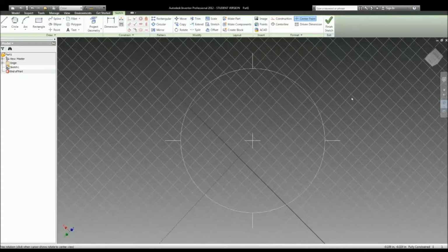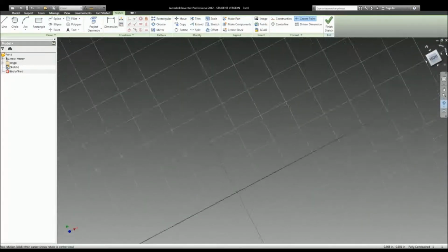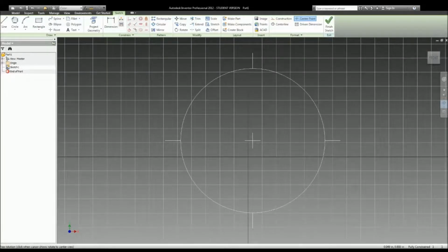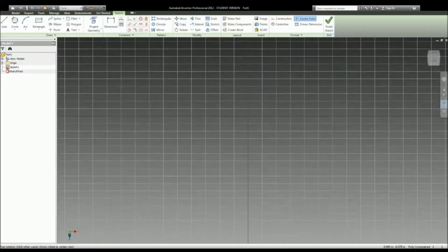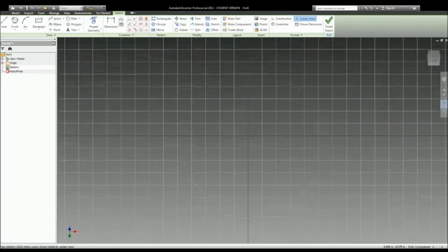Okay. I'm going to reorient back to the front, and I'm going to rotate it 90 degrees using these curved arrows. And then we have the top and bottom lines and the left and right lines. It's exactly as it implies. If you're over the top or bottom line when you click and drag, it rotates your object on that specific horizontal axis at that center point.